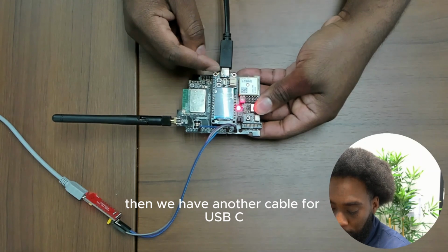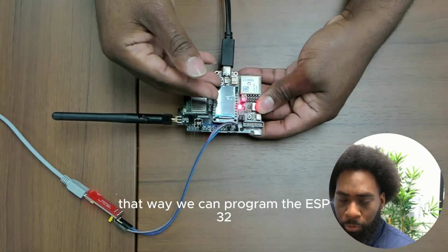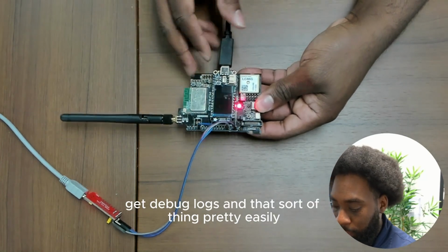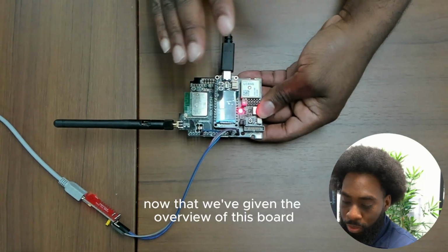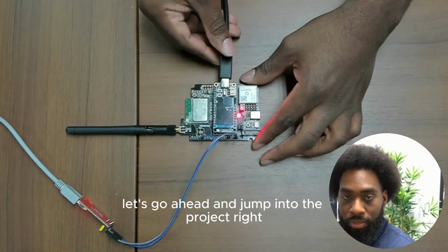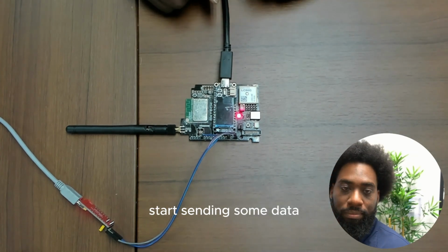Then we have another cable for USB-C to the Feather platform. That way we can program the ESP32, get debug logs and that sort of thing pretty easily, and also power the rest of the system. All right, so now that we've given the overview of this board and what's connected to it, let's jump into the project and see how we can take the project and start sending some data.